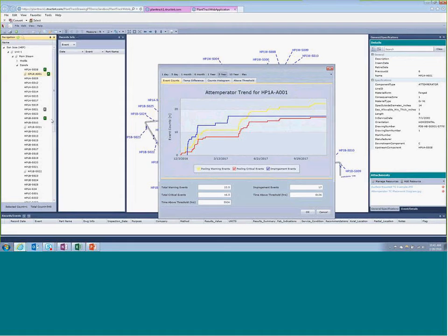And again, this is the same concept as the creep and fatigue monitoring, in that we track the actual top to bottom temperature differentials, and that establishes criteria. We set criteria to then basically count those particular events that exceed those differentials. And using that type of logic, we can differentiate between pooling, impingement, et cetera.